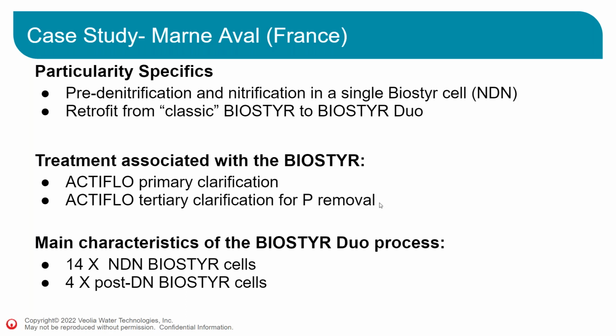The second case study, we don't have results yet because the site is still in commissioning. It's Mar Naval. One of the particularities of this project is it was a classical Biostyr for denitrification, nitrification, what is called NDN. They had classical Biostyr and they decided to switch them all to Biostyr DUO. So right now what they're doing is they are getting the last Biostyr cells down to DUO cells.